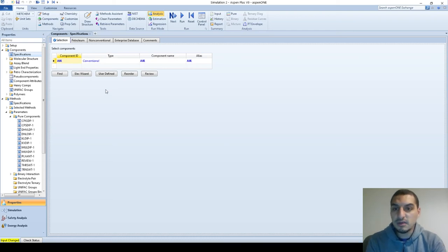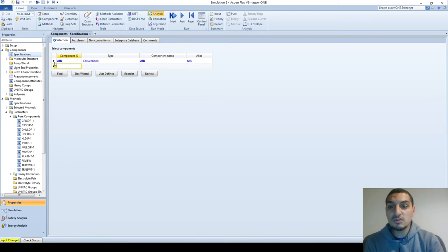Hello everybody. In this video, we're going to talk about the compressors as one of the components that we have in the pressure changers. And the problem that we're going to solve today is just an air compressor. So we have here air as the component, and this might not be a very well known information that you can define air as a component that's already there in the software's data bank. So you don't need to define it as oxygen and nitrogen, just air if you are using it as air.